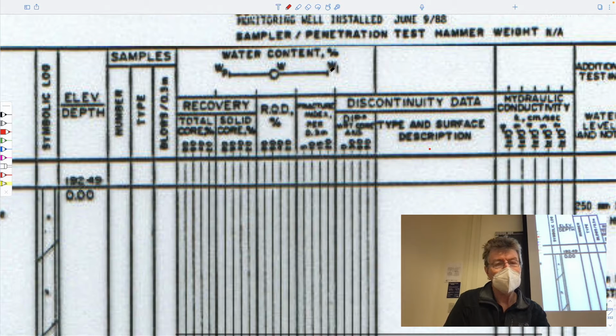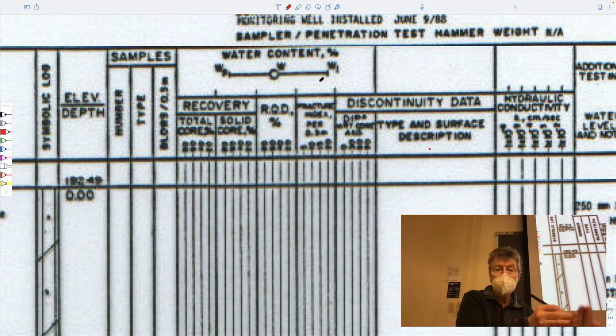Very bizarre experiments. The liquid limit is when you add enough water to the clay that when you put it in a little dish and drop it about an inch ten times, a slit that you put in it closes up. Really rudimentary test, the so-called Atterberg limit test. So the liquid limit is when it flows like a liquid. How much fluid do you have to add for it to flow like a liquid?